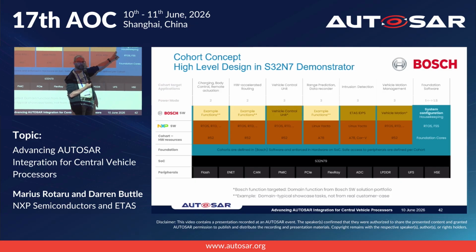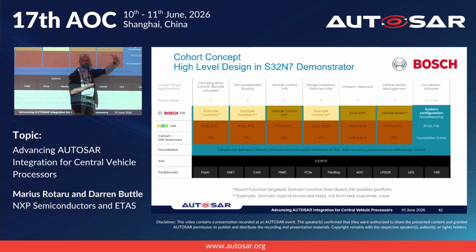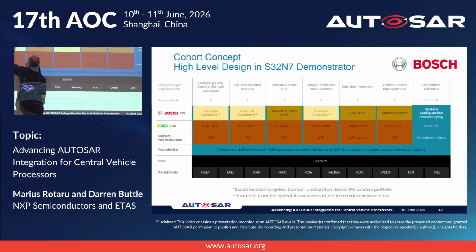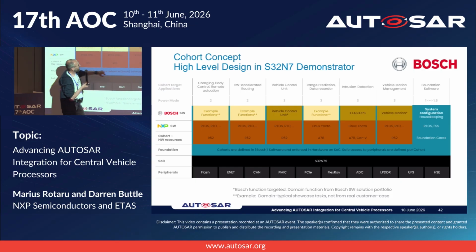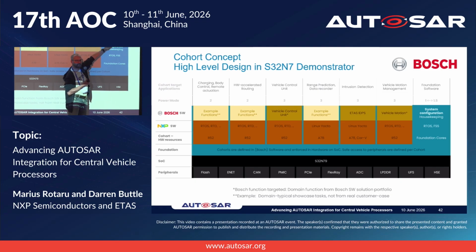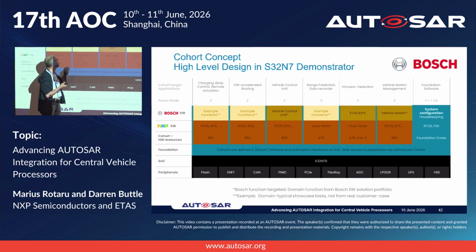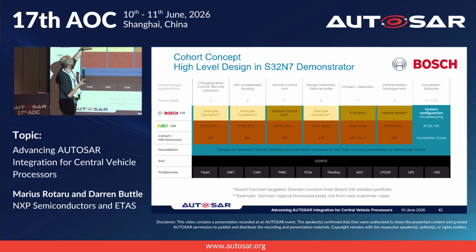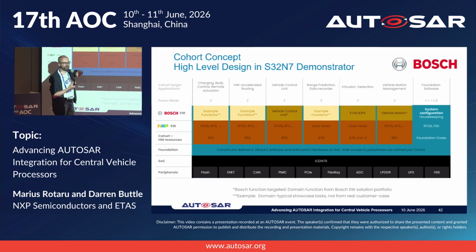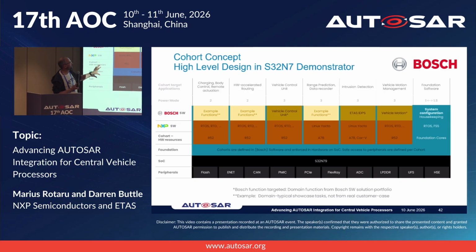This is the hardest bit to actually engineer. This thing is sort of business as usual, but this is introducing a new category of problem in terms of ECU management. And then you can see here, okay, what comes up in what sort of power mode. So clearly in the low power modes, the foundation subsystem boots first, that chip runs, and then that's responsible for making all of this other stuff come up and come out of boot. And you've got these, the body and the hardware accelerated routing come up first, and then the rest of the things.